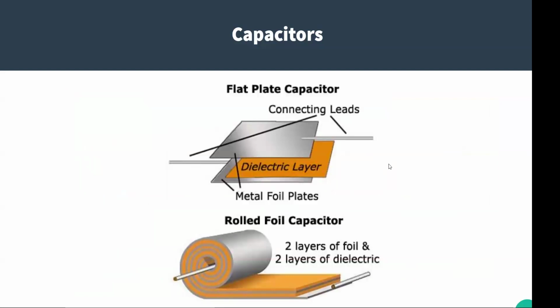The electrolytic capacitors in older electronics have a tendency to blow up. So that's one of the things that you're looking at whenever you try to restore something. Like I've got an old console stereo with the turntable and everything. Before I fire it up, I want to replace all those capacitors, because if you try to put power on them when they're 30 years old, 40 years old, they're probably going to explode.